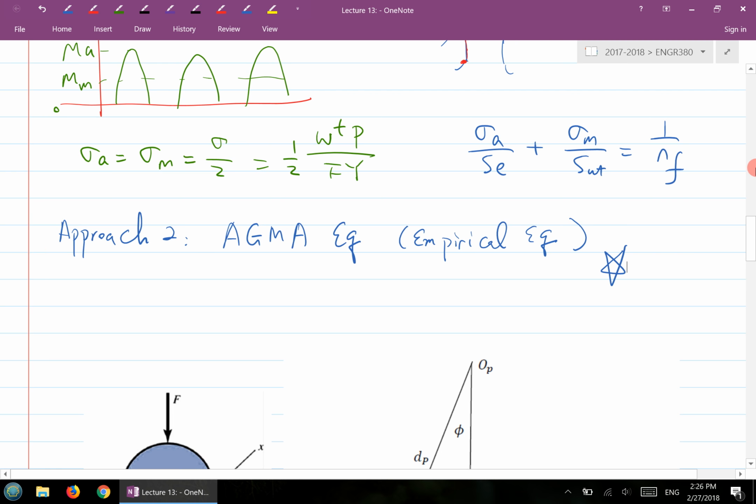So when two gears engage each other, there's constant pressure applied between this pair of gear teeth, and that load, that force, ultimately will result in surface failure. That's basically the second type of stress we're going to look at here. So we're going to look at the contact stress.